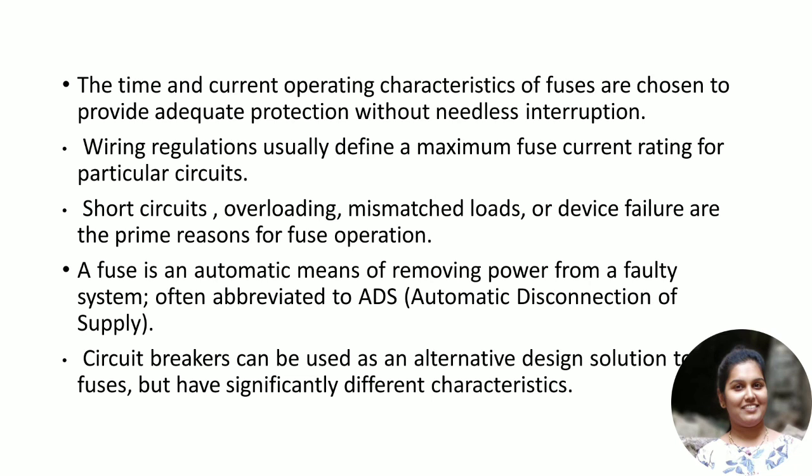So we'll take the power and voltage rating capability of the particular load, and with that we'll be multiplying with the constant 1.25 value. The result we get is the rating of the particular electrical component. So that value will define that much amount of current that a fuse can withstand, and that much current that component will withstand.